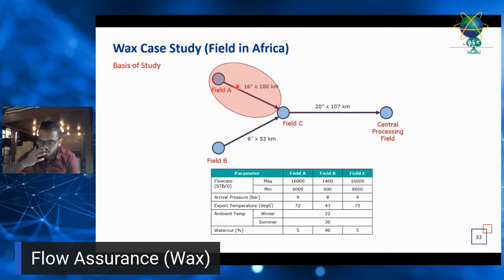So how did they recover this flow line? Since the whole section had gelled up, in the middle of the savanna, they dug up the soil, a kind of pond, and they hot tapped the pipeline.